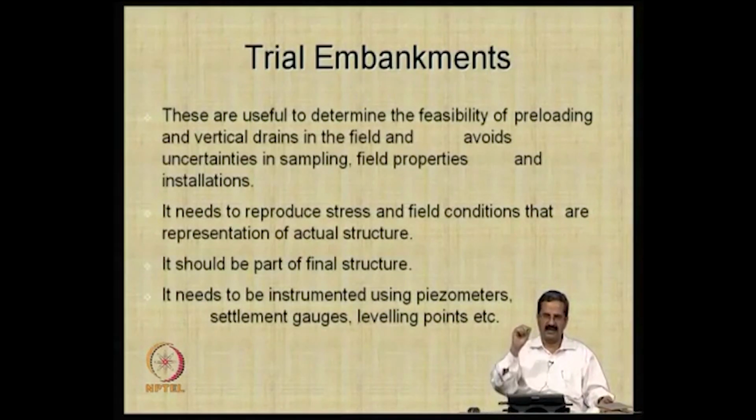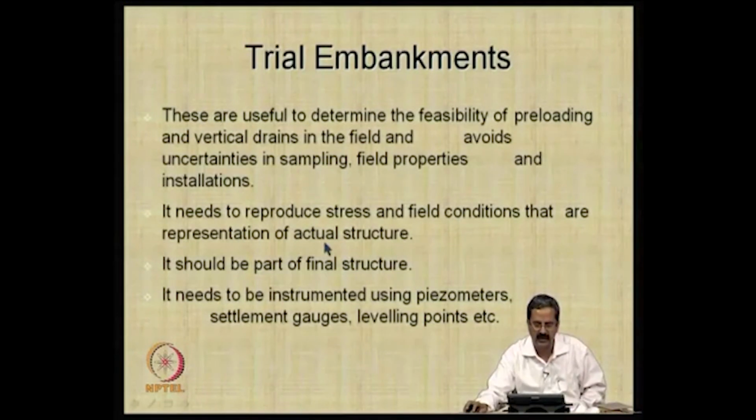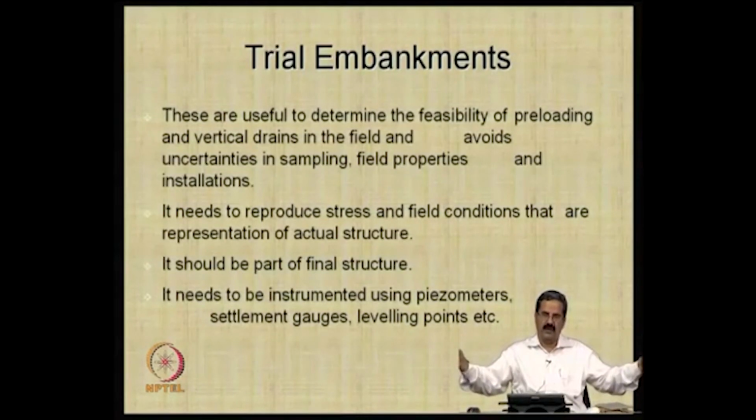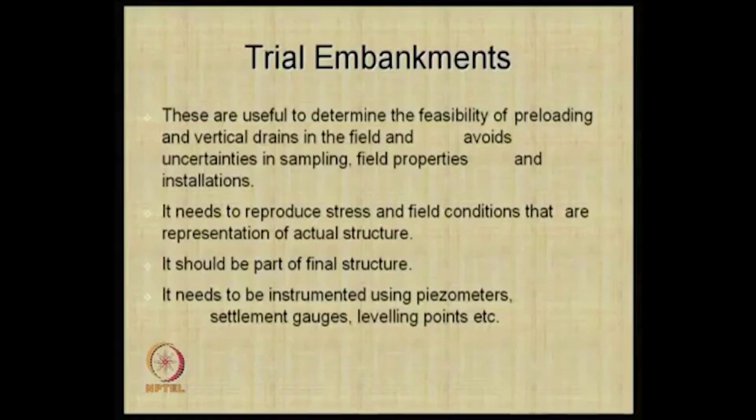Once you understand everything from that, it can be used as the input for improving the rest of the work. That is what we are trying to do here. It needs to reproduce stress and field conditions that are representative of the actual structure, so that you can use the information you get from it in a proper way, and it is better if it is a part of the final structure. For example, if the alignment connects 2 villages over about 20 kilometers, then 50 meters of it could be a trial embankment.